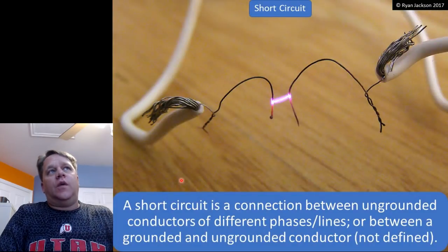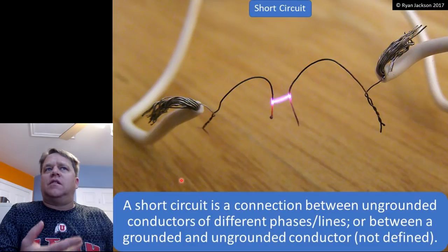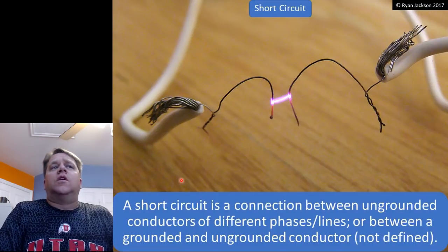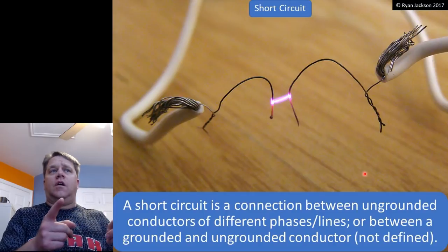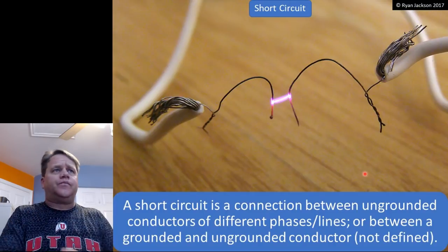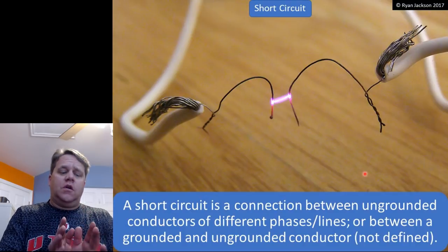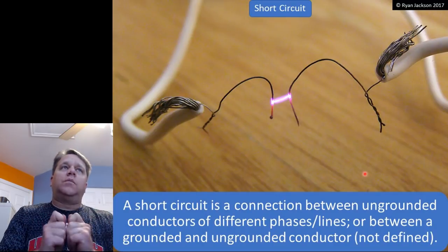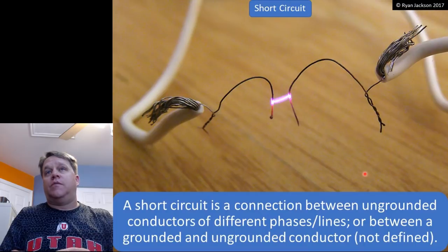The other type of overcurrent that we have is a short circuit. Now, this is not defined in the NEC, but a short circuit is basically a connection between ungrounded conductors of different phases or lines, or between a grounded and an ungrounded conductor. So here we have two different conductors of two different polarities, right? So two hots, phase A and phase B, line 1, line 2. And they touch each other. That would be a short circuit. Those are the three types of overcurrent conditions: overloads, ground faults, and short circuits. When we provide overcurrent protection, we're providing protection against all three of those types of overcurrent.